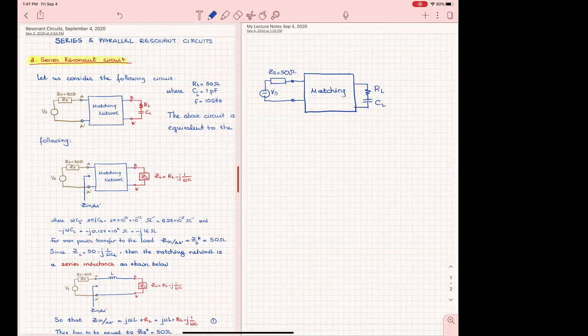All right, so do you remember what we said about what kind of impedance we want here to create the maximum power that goes to the load? It needs to match the source impedance. It needs to be the complex conjugate of the source. Remember that? Never forget the complex conjugate. So practically, what does your impedance do?